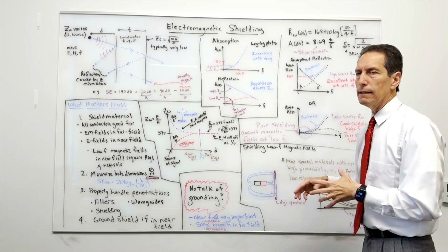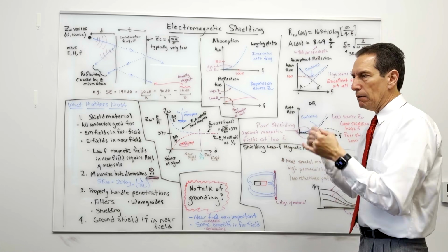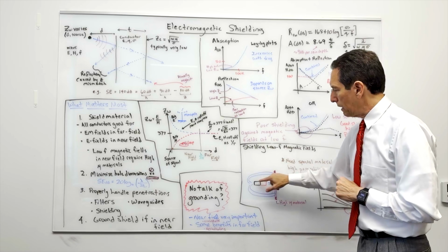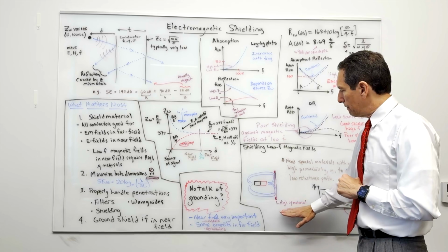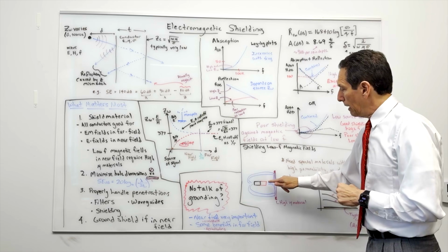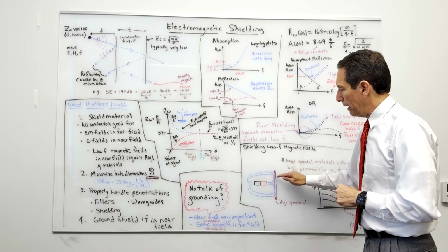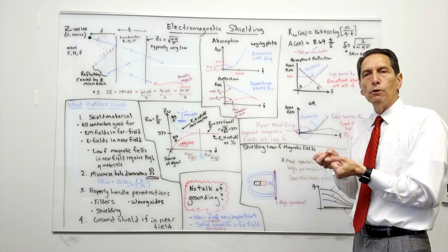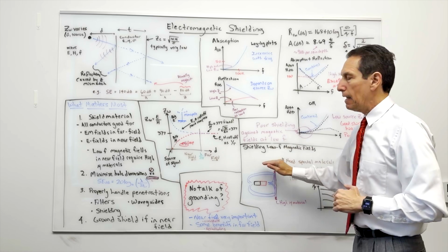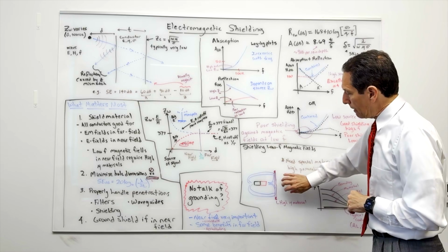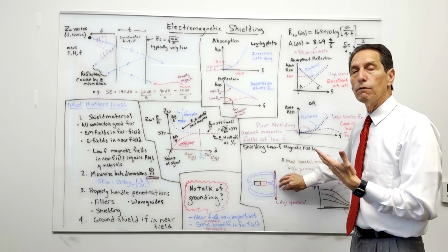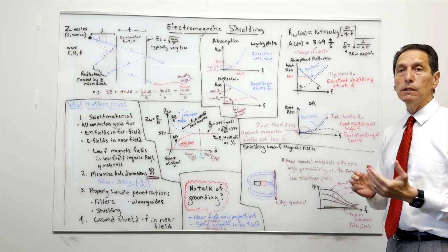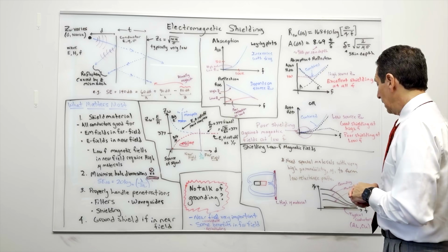If you think about a magnet, and let's think of that as a time varying magnet where its magnetic field's changing. The magnetic field lines, of course, go out one end and come in the other. But if I put a barrier of this very high permeability material, it will steer the magnetic field lines through it and then let them route back around. Rather than let them come through, it will sort of capture those magnetic field lines and collect them and let them close their loop the way they're supposed to. And that means on this other side, you don't see the magnetic field, or not as much of a magnetic field as you would have, all right? But you have to have these high permeability materials, which are typically very expensive to use in shielding.